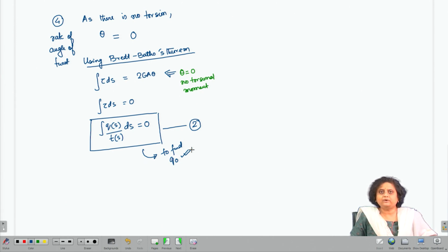So, we can always find the shear flow due to this additional torsional moment and add or subtract it, based on the sign convention, with the shear flow from the shear forces and get the total shear flow in the cross section. So, this is the methodology that we are going to follow to find the shear flow in a closed cross section beam.